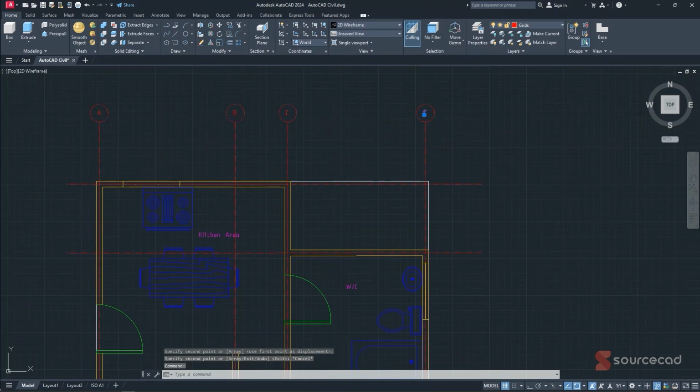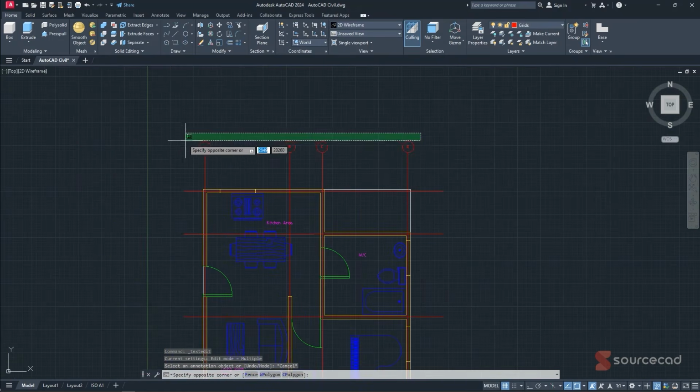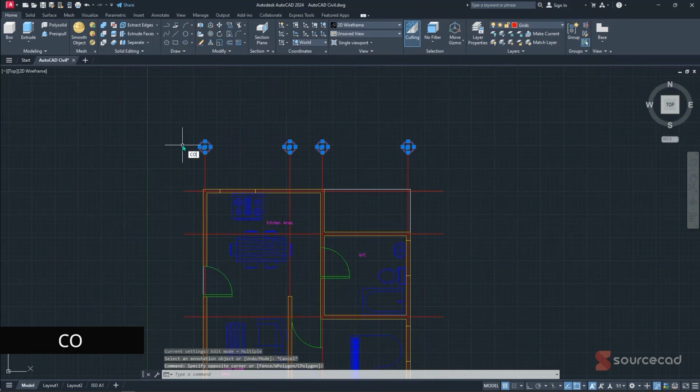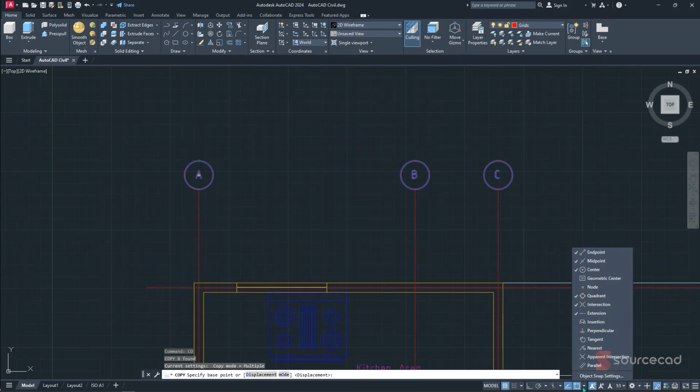Double click inside and edit it to D. Then click away. So what we're going to do is very easy. Just highlight this. Then Ctrl+C to copy from this point of the quadrant. If you cannot see this option, simply click on this option here and you'll see quadrant. So make sure this one is checked.